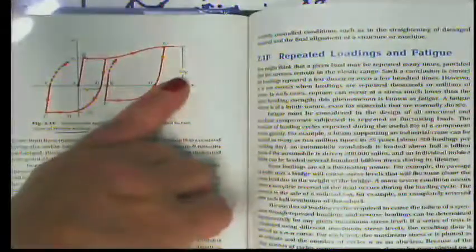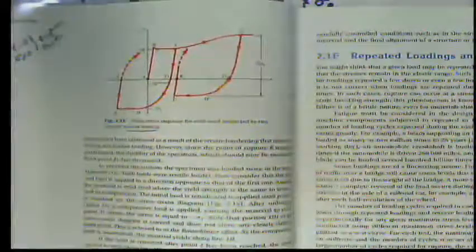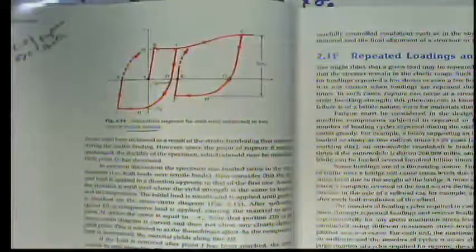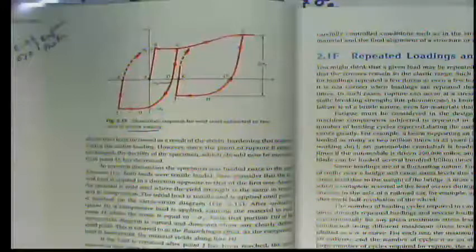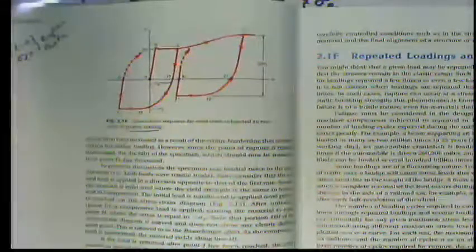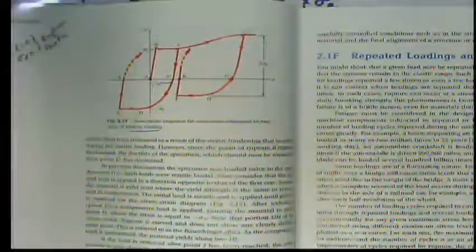So if we pull it past its yield and press it again, it becomes brittle? Mild steel does. That's right, and most materials do. The real message for these graphs, they're all different. Every material behaves differently after you exceed yield. The real message I always tell my students is, don't let this happen to you.